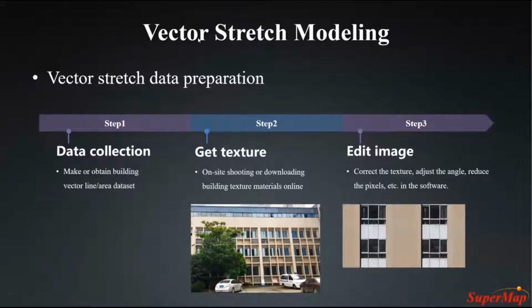So let me introduce these preparations. The first step, you should collect the data. That means you could make or obtain your building vector dataset and import it into SuperMap Desktop.